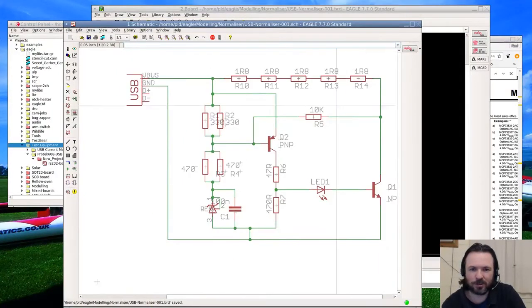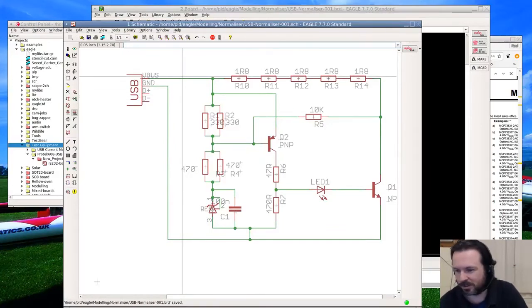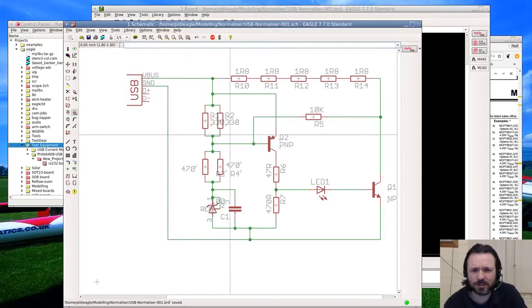I'll give you an explanation of how it works, at least in theory. The very first thing that goes on is when we get our battery voltage, say 4.2 or whatever, it'll come on down through here, and this is set to be about a 2.5 volt reference, so the difference is then split between this divider. The reason why I have two resistors in each is so that I can trim them so that I can compensate for differences in the transistor.